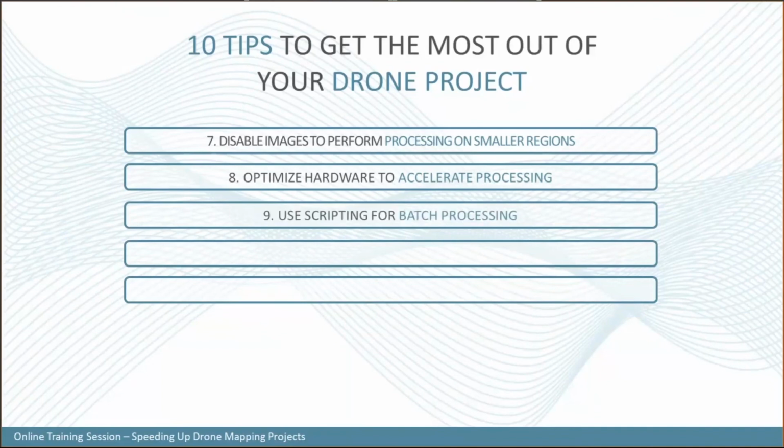If you're processing similar projects throughout the time, start scripting for batch processing. It's probably something that will save you a lot of time. So maybe you want to take a look at some of our webinars we did specifically on scripting, so you can run different projects directly without any human interaction. The scripting can be done from the project creation up to the deliveries. So everything can be scripted out without even launching the graphical user interface.